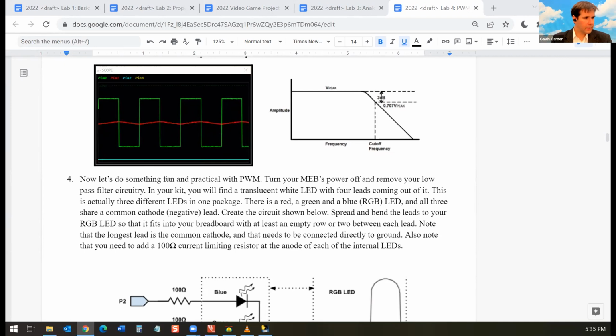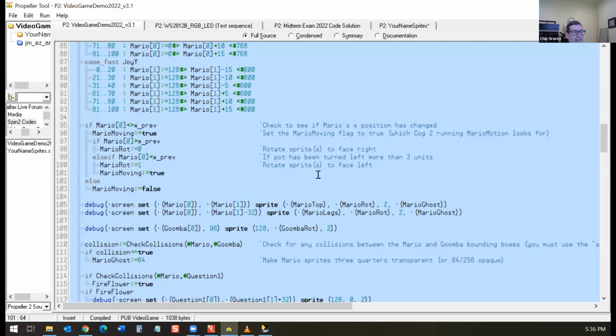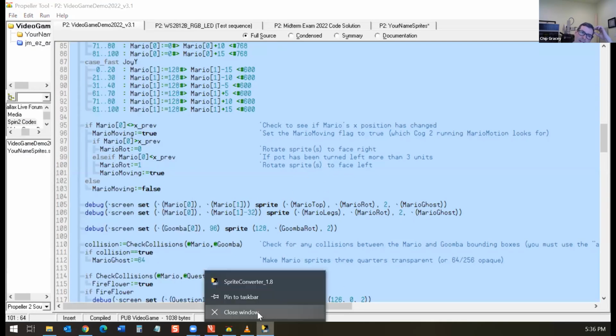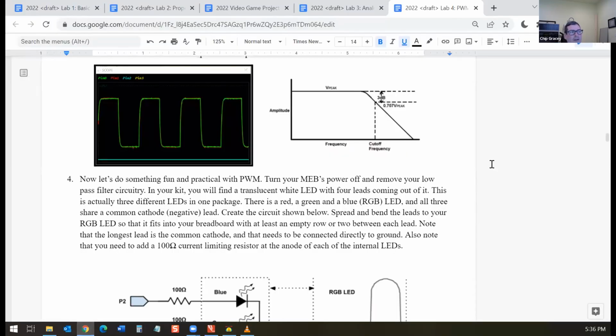Got it. Okay. I was wondering about your keyboard and mouse demo, which I haven't really dug into a lot. You have it plotting dots as you move the mouse around, but there seems to be a bit of latency. Is that a result of the... There shouldn't be. I mean, we could put a delay in there. The latency may come from the input buffer on the PC getting bigger, because the data is not being utilized, so you wind up with a phase lag. If you put a little pause in the loop of the drawing program, it'll sparse out the data so that it doesn't overload the PC. Oh, I see. Okay. The PC can receive the data and process it, but Windows takes a while to draw everything.